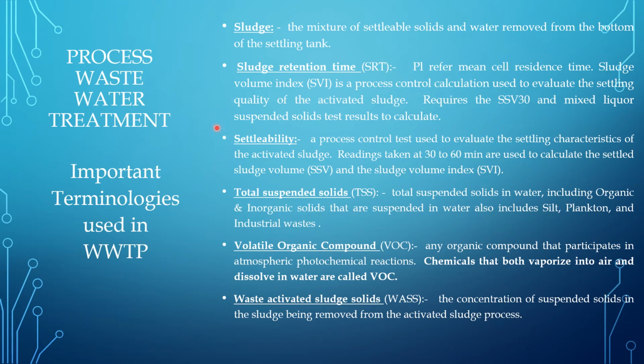For that, we have to adjust the DO and we have to adjust the volume ratio also, so that the activated sludge volume will be maintained. Total suspended solids: the total suspended solids in water, including organic and inorganic solids that are suspended in water, also include silt, plankton, and industrial waste.